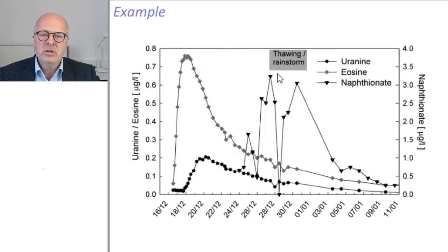So from that moment on we knew that the source of the pollution was actually lying on the line between the injection point and the spring. So we started to search and we found it. It was a buried creek, so they just wanted to fill it, and they filled it, but the creek in fact was still active and still contributing water from the road. So everything had to be excavated and refilled correctly, and afterward the problem was solved.